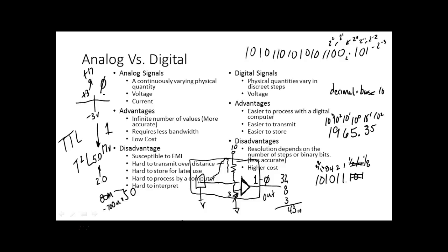And you didn't have to worry about the ground shift, because why? Because you had such a big range. So if you shift 1 volt this way and you're using 15 volts, your receiver would see it as a minus 14 and a plus 16, which is still what? This wasn't 17, guys. This was 25. It was a plus 25. Plus and minus 12 was the most popular use.